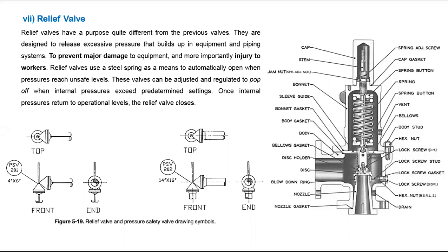Relief valve, you can set to any level of pressure. No problem. If you want to set it to 0.5 bar pressure also, you can use a relief valve. So we can adjust pressure here. Yes, you can adjust by adjusting the screw. You can adjust the pressure for 0.5 bar, 6 bar, 4 bar, 3 bar. You can adjust and test how much pressure is required, based on your requirement only. Okay, thank you.